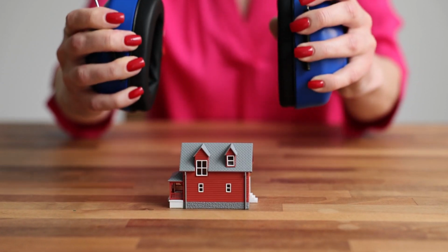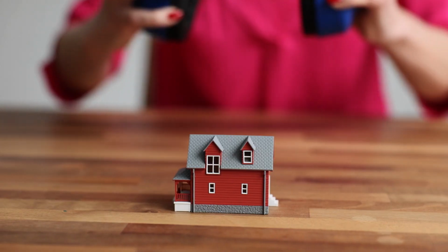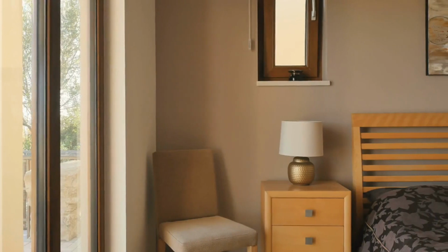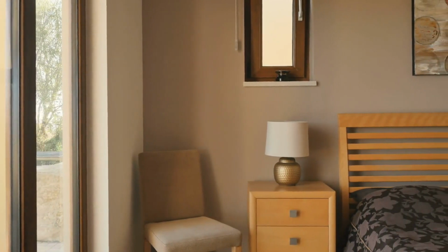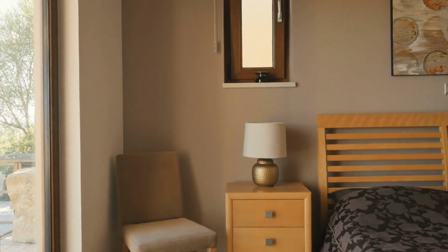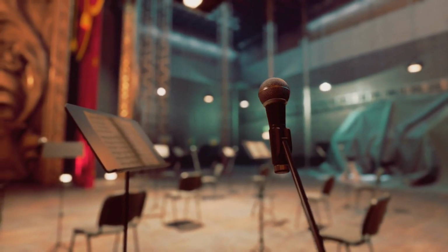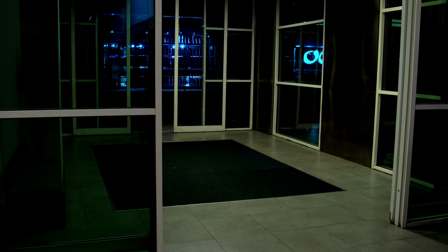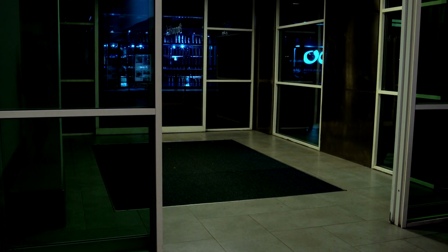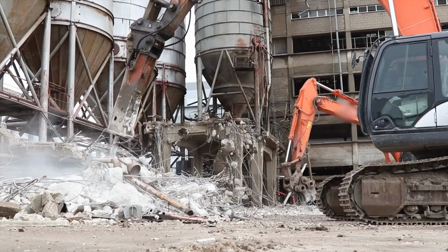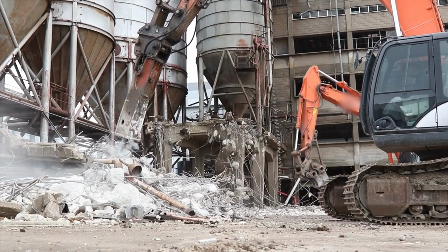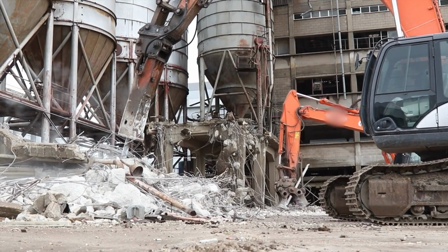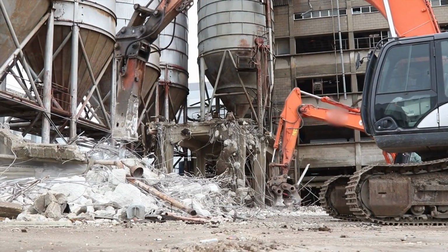Case studies. Practical applications. Converting a bedroom into a studio. Converting a bedroom into a functional home studio involves a combination of soundproofing and acoustic treatment. Start by analyzing the room's acoustics to identify problem areas. Soundproofing efforts should focus on sealing gaps around doors and windows, adding mass to walls, and potentially installing a floating floor if noise transmission is a concern. Acoustic treatment should address first reflection points with acoustic panels, corners with bass traps, and the rear wall with diffusers.